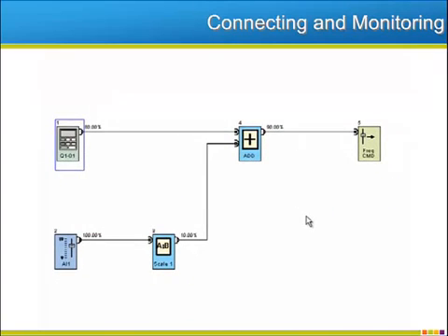This shows the instantaneous values of all the inputs and outputs of all my function blocks. So my potentiometer is used to trim my speed reference anywhere between 70% and 90% of my max speed.